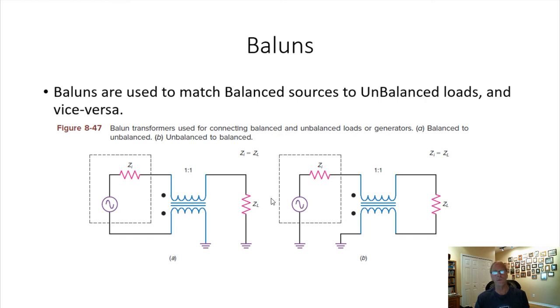But if you want to connect one to the other, the best way to do that is using a balun. And this is a balun. This one is matching a balanced input to an unbalanced load, okay? Now you can also match an unbalanced output of something to a balanced load. Okay, so it works either way. All right, baluns are often used again in audio systems and in RF systems to match balanced to unbalanced.